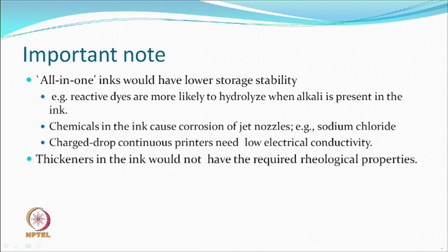Thickeners in the ink may not have the required rheology, because you require low viscosity. So, if at all you require some way to control diffusion, then again it is not a good idea to have any such thickeners very easily in the ink. So, rheological properties will be affected, but the rheology which is required is of low viscosity systems, but still has to be controlled.